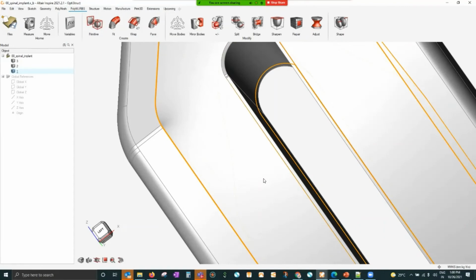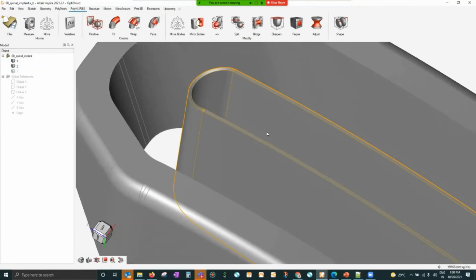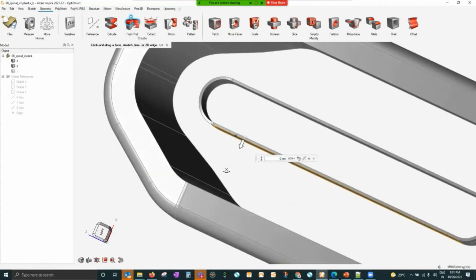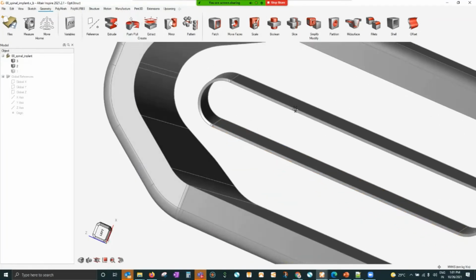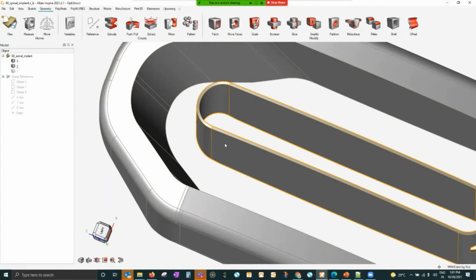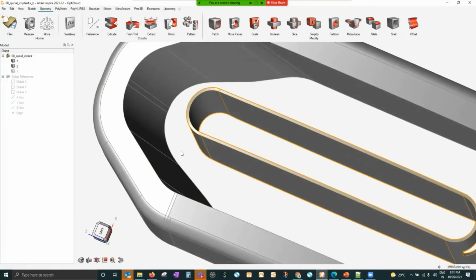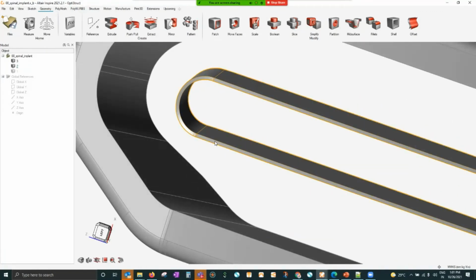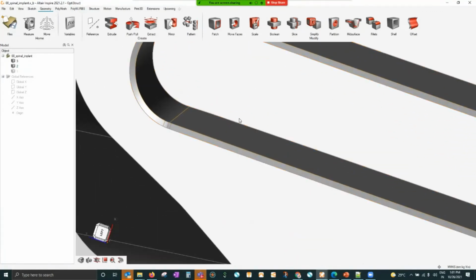If I hide this and go to geometry, and let's say set 5, you have to make sure this wall thickens up. While modeling, you have to make it thicker, and that will give the lattice enough space to be within this boundary. It is very thin, that's why the lattice is coming through. If you make it thick, the lattice will not cross.